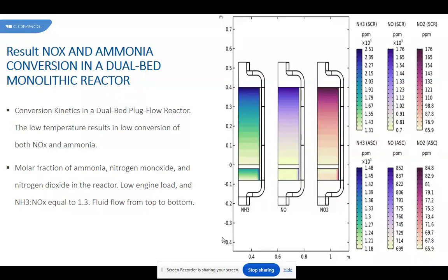The two mentioned variables show a positive or negative correlation depending on which part of the substrate, core or ring, has the highest permeability. These and other results contribute relevant evidence for further monolith optimization. The catalytic converter forms the basis of the automotive exhaust gas aftertreatment system used on most passenger vehicles in Europe, North America, and other regions to control emissions such as carbon monoxide, hydrocarbons, and oxides of nitrogen.